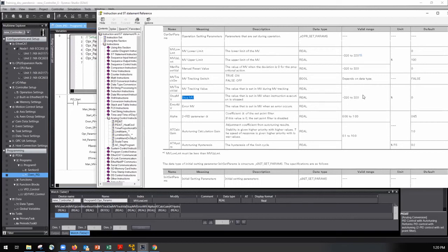So this is specified in a percentage, which is something I'm not going to say unique to Omron, but perhaps different than a few things that you guys are used to. So it's a percentage of our output instead of a hard-coded value. If my output was 0 to 100, and I specified 10% here, then that would be 10. But if my output was 0 to 300, and I specified 10 here, then it would actually be 30.